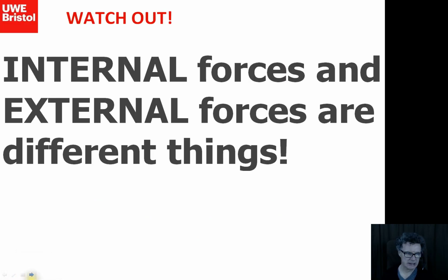So finally, watch out. It's very easy to mix up the concept of an internal force, which is happening inside the bar, and the external force, because with the method of joints we've cut through them and we've exposed those internal forces to you, and we're doing calculations all over the place which are involving internal forces and external forces, and we're saying that they're going to have to balance. But don't forget, they are different things. The external forces are the things that are being applied to the body. The internal forces is what's being experienced inside the body.